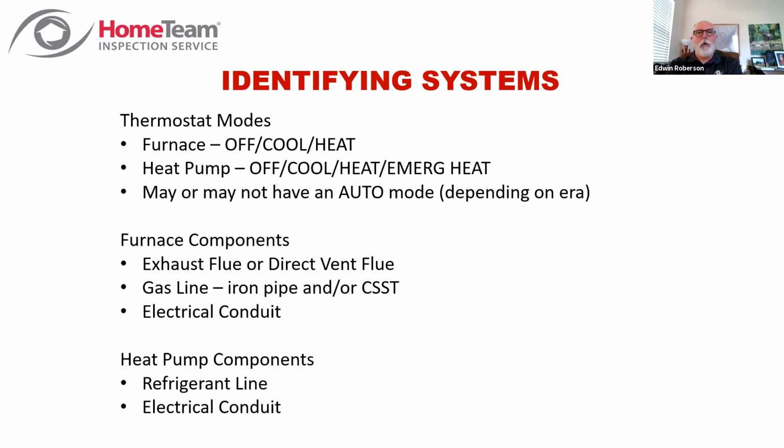But we came along, in our inspection, we found that you had a furnace type thermostat on a heat pump system. Well, now, if you remember talking about those digital thermostats and the smart thermostats, they're programmable. That's a very easy fix. It's not like you have to replace the thermostat, but if you get into older systems, you may have to. Well, if you get into older systems, you probably need to replace the thermostat anyway. So when you go in, emergency heat or no emergency heat is your first clue to the type system you've got.